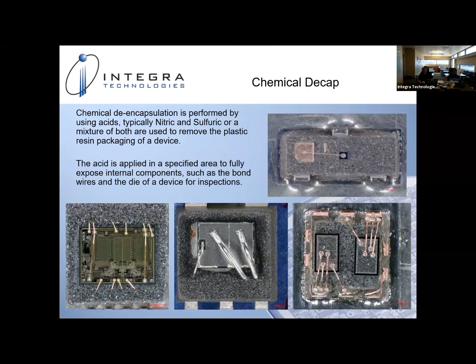And here's the final product, optical imagery of some chemical decaps that we've done. So after laser ablation, we can mix some chemicals. It could be nitric, sulfuric, a combination of both, or one standalone. As mentioned, we create the trench or the cavity. The acid is applied, and we apply enough acid so we can expose the internal die as well as